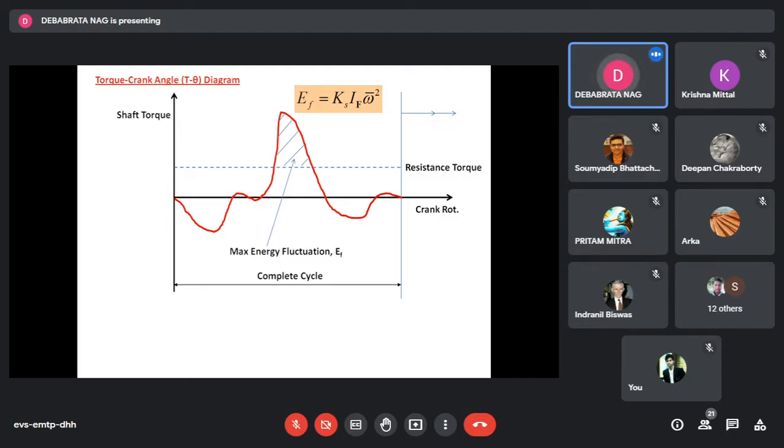Omega max and omega min, which is tolerable by the system. If it exceeds, then the system will be cut off from the supply and there will be a massive outage of power. It happens many times in different cities, including Kolkata in the past.